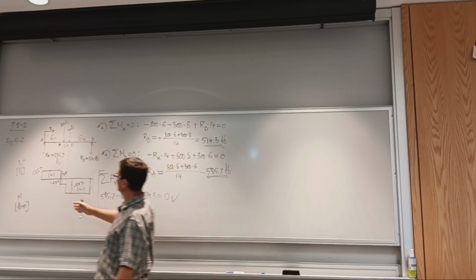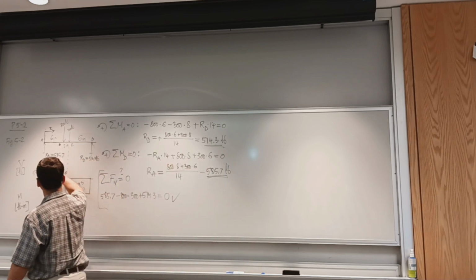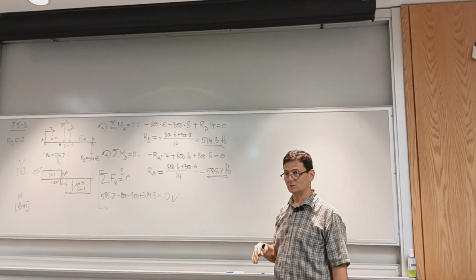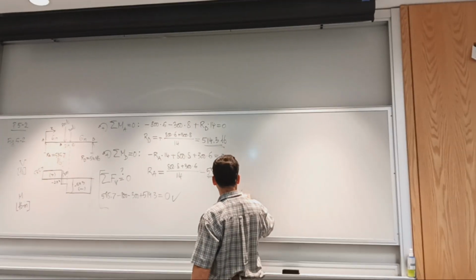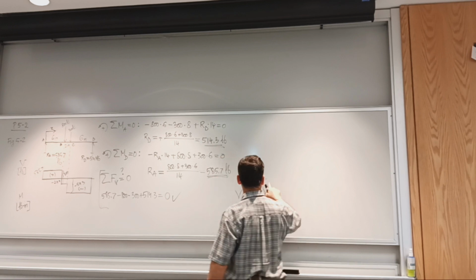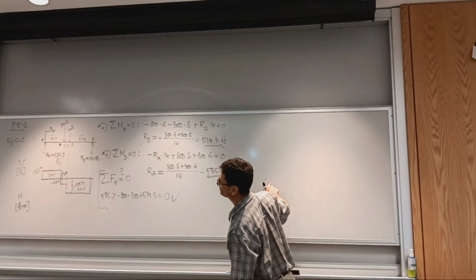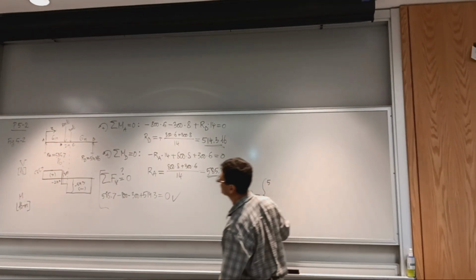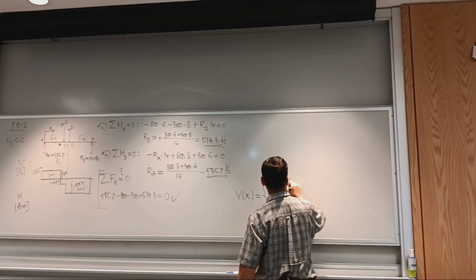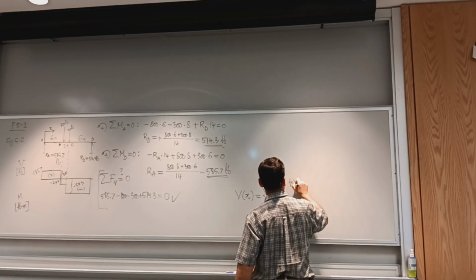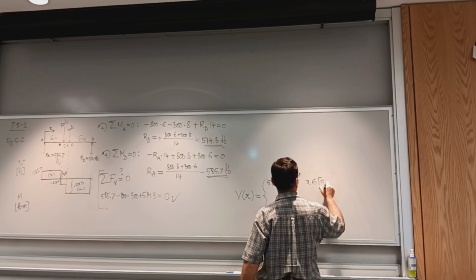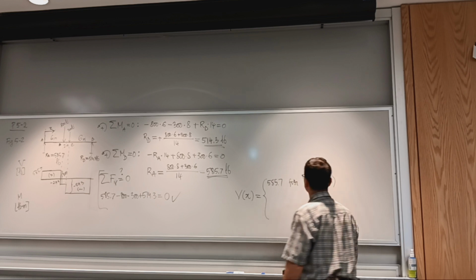The problem 5 actually says write equations of these curves, and we can do it now. I can put this diagram in math form, which will be a piecewise continuous function. So I can say v of x equals, I have how many? 3 pieces. So it will be positive 585.7 for x belonging to 0 to 6.